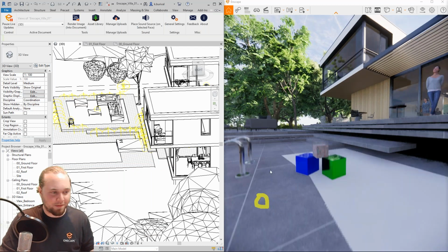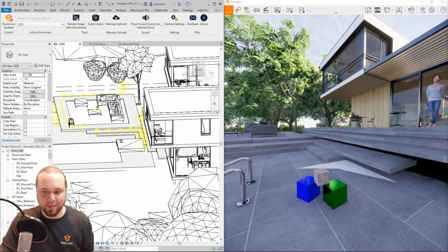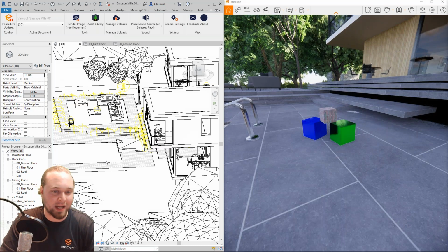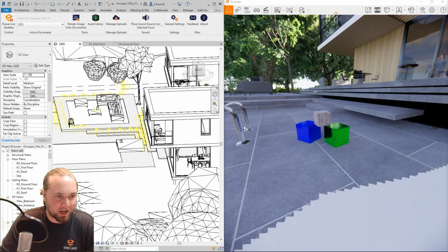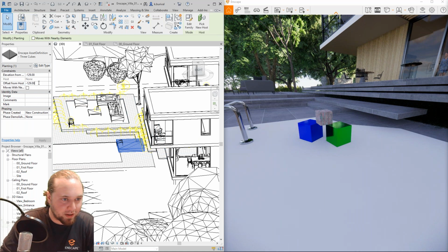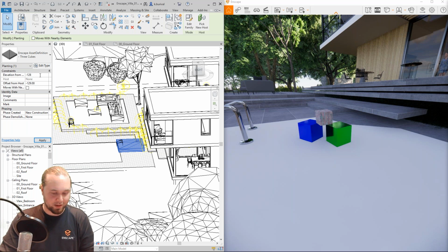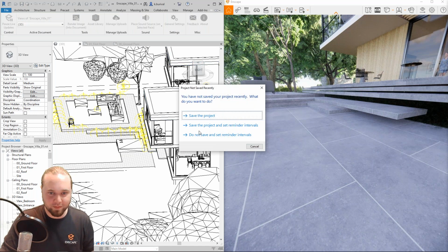Currently flickering a bit. By the way, that happens when one surface overlaps with another surface in any kind of application right now, because our floor or both our floors are on 0. In those cases, it's really helpful if we just offset it by at least 1 inch or 1 centimeter or something like that. Let's see. Oh no, I've deleted it. There we are.